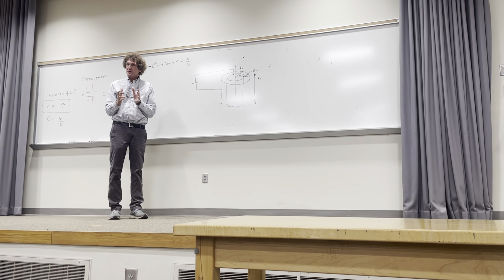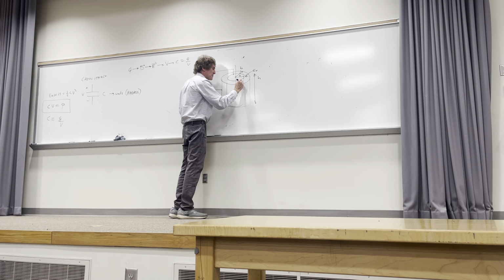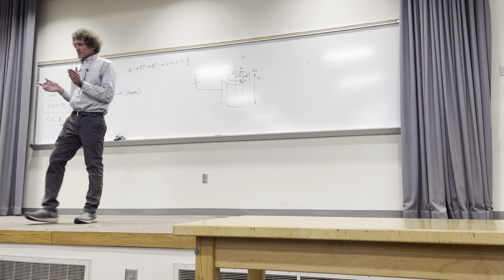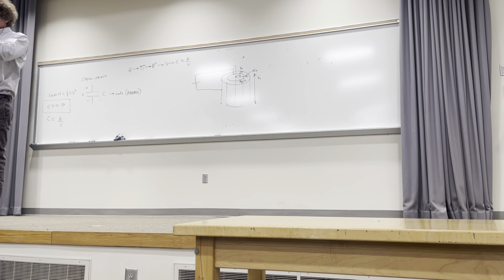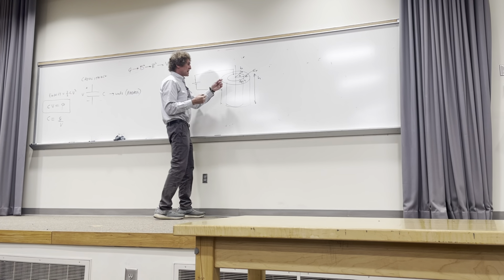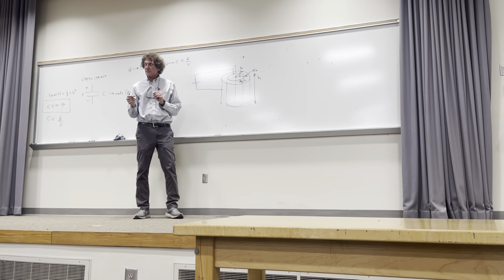Two hollow cylinders, and there's some dielectric material. So the capacitance is here, right? It's really between the inner and outer surface. When I gave that resistance problem on the quiz, people were trying to get the resistance of current flowing along the axis, but I wanted the radial resistance. That's the big difference. Make sure you understand what we're talking about. This is the capacitance between the inner and outer radius, and I'm trying to show it like this. Can you all visualize this?